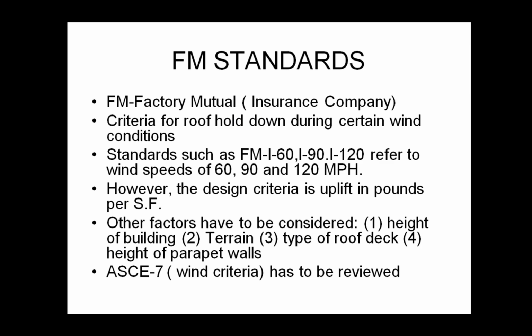And again, the design of your roof and the roofing material have to be considered together. Right, the higher your building is, obviously you want to live up to the higher standard because you're exposed to higher wind speeds up there. The height of the parapet walls are important because those serve as a barrier to wind. Okay, so if you have a higher parapet wall and you have almost an enclosed 7-8 foot high roof deck, a lot of your equipment and your roofing material would be very protected from that wind, and that's ideal. And again, just putting up parapet walls is extra expense on the building, extra materials, but it could actually be beneficial for the life of the roof.